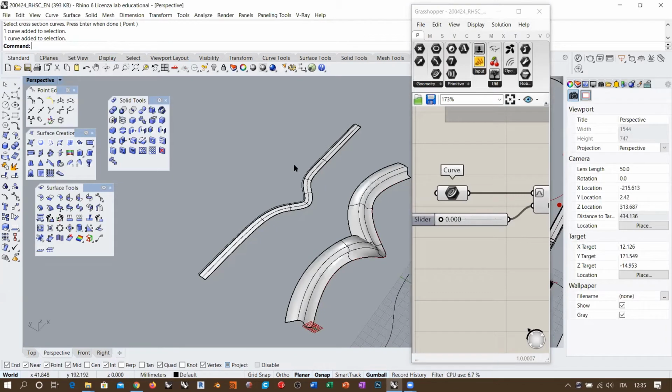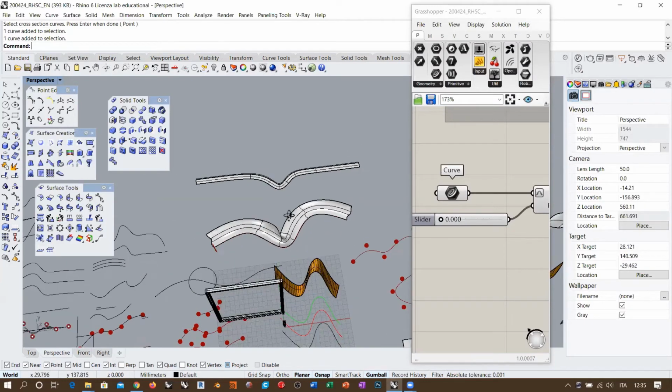Other things that are affected by this consideration are, for example, the offset of a surface. The offset of a surface is a little more complex, because a surface has not only one curvature value, it has 2 curvature values, which are also considered in combination of the two in 2 different ways, in terms of mean curvature and Gaussian curvature. They are 2 different meanings of the curvature analysis of a surface.